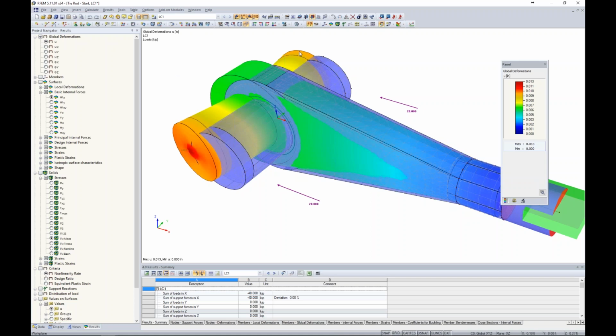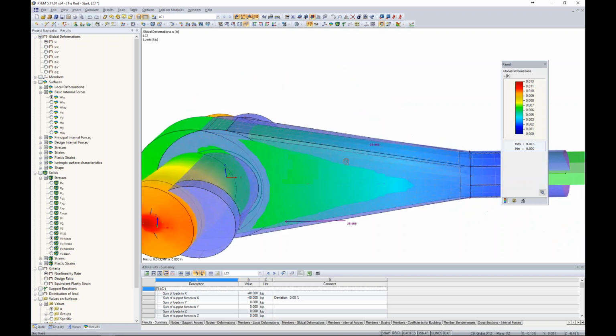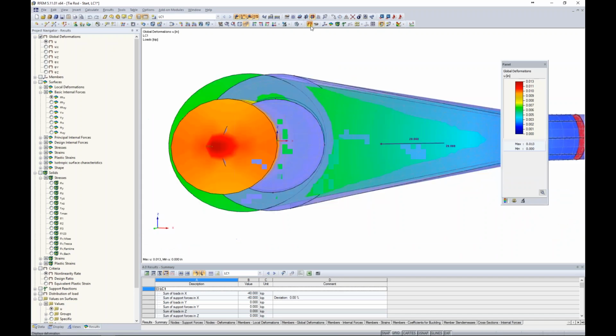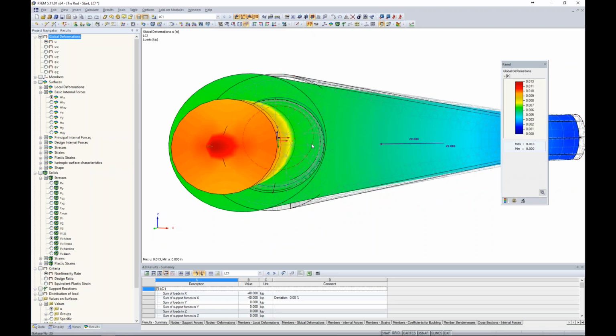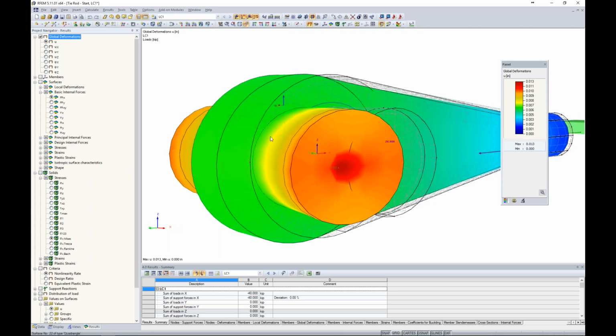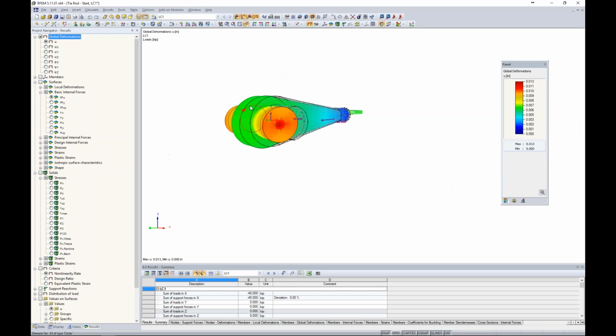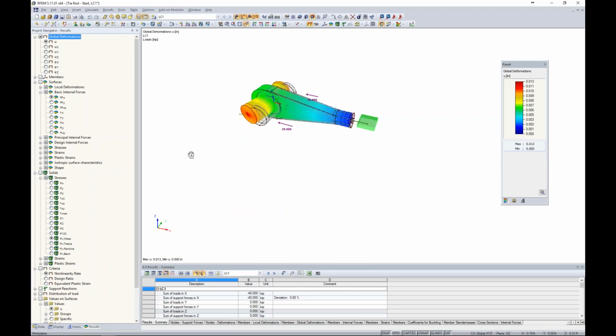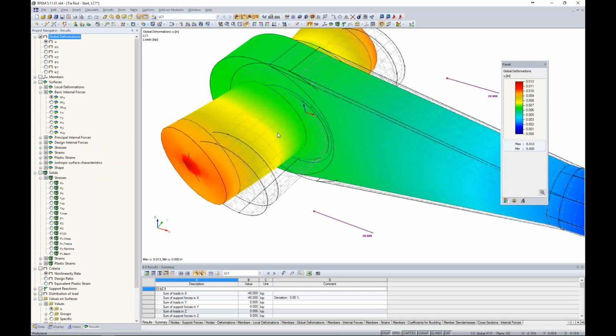So with this bolt element passing through the eye, and we turn this into elevation view and maybe into wireframe, we can see here that it looks like the bolt is fully fused to the front portion of this ring element. This is not really what's going to happen. In reality, what we would hope to happen is that this bolt would release away from the ring element where we have tension forces, but in the back, we would still have full fixity here where we have compression where the bolt's bearing onto the ring. So how do we exactly take that into account?